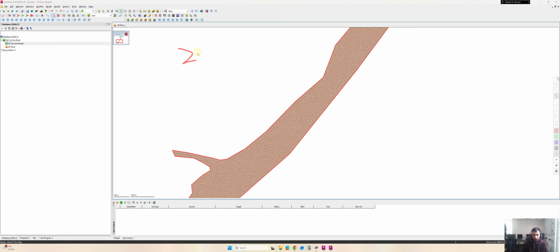First we have to define the 2D zone. After that, the 2D boundary for the inflow, and then the third one is the mesh generation. So these are basically the 3 points that you have to keep in mind in order to create a 2D river model.